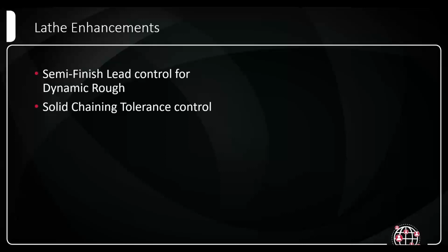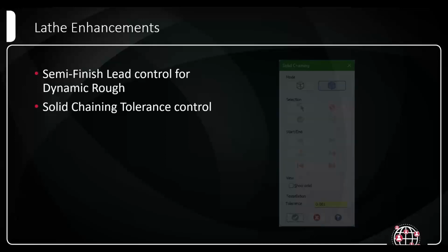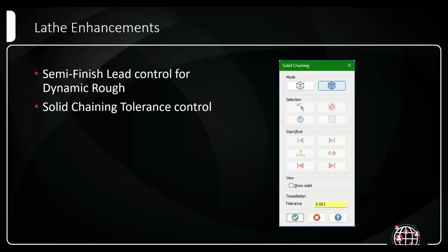In an older version of Mastercam, what we had to essentially do is stop what we were doing, go into the configuration and change the tolerance within the configuration. Now though, in 2024, they've added the tessellation tolerance right here into the chaining dialog. So if for whatever reason you need a much tighter representation of your part for the job you're doing, maybe there is a 5/10 chamfer, you can drop that tolerance down.